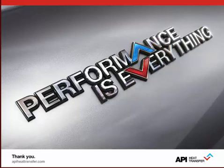All right, thanks, Chris. Another question here. When is it advisable to use baffles, and what are the determining factors for the best design of baffles? Well, baffles are always advisable to use. If you don't use baffles, you're not getting a good mix of shell side fluid. There are cases where specific types of baffles are used or not used, where that type of turbulence isn't required. But for the most part, you're always going to have some sort of baffle.